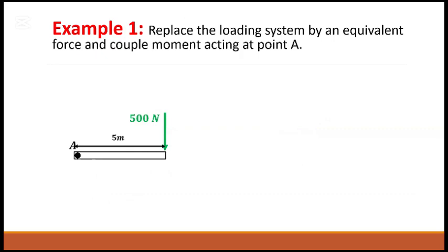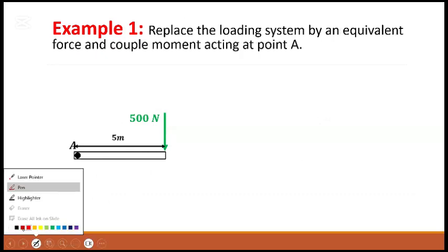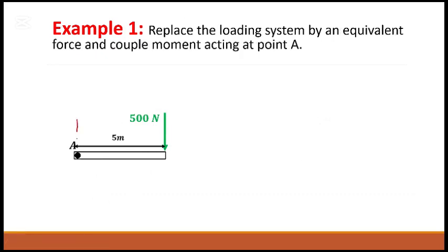Now, if I just apply another 500 here and another 500 here, have I done anything to the structure? No, they balance out. It is canceling out, isn't it? Yes. So this is the same structure that I had with the same forces. I haven't created any effect.